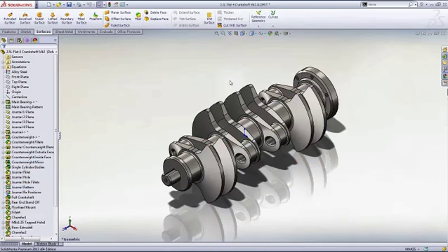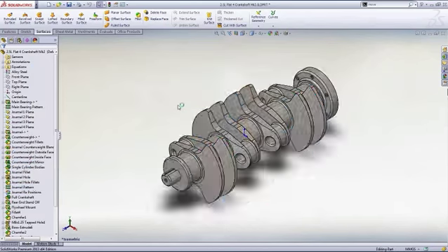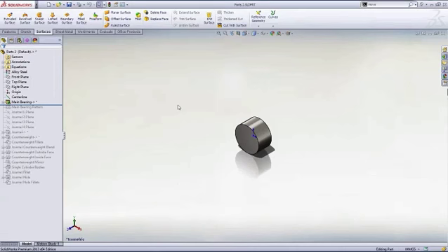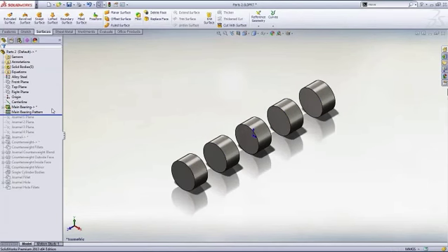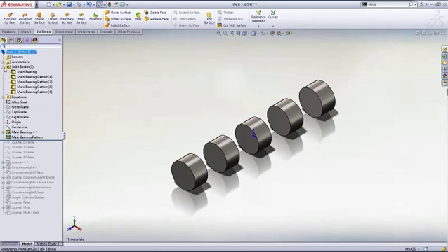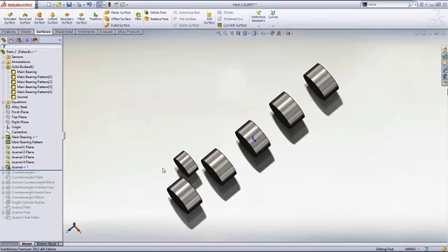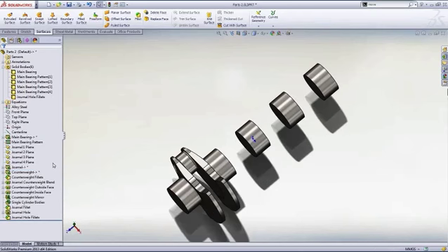I'm going to open this design in an earlier state to explore this concept. In this design, I've started with a simple cylinder for the bearing surface. Then I've patterned that, and you'll notice in doing so, I've created a part with multiple bodies. In fact, when I did this, SOLIDWORKS revealed a folder containing all the individual solids. Next, I created the journal where the connecting rod attaches out in space, also as a separate body. This method makes it really easy to get the basic geometry created and then just fill in the rest with a connecting geometry, in this case the counterweights. I've also intentionally left the counterweights in the journal unmerged from the bearings, and we'll see why I did this in a moment.